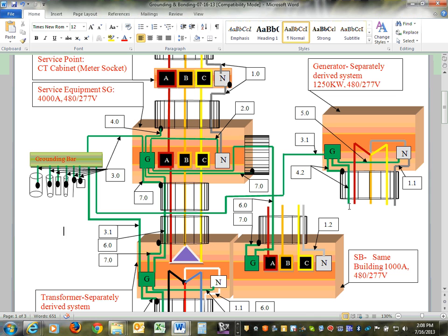So these are typically, guys, if you deal with parallel switchgear, you take your power out of these beasts, 1250 kW, in a conduit, and you land them into a parallel switchgear, and your first circuit breaker will be located inside the switchgear, right? Draw-out switchgear. If you have a smaller emergency generator sitting there, your circuit breaker disconnect will be located right at that generator. In a case like this, that 4.2 is going to be called the equipment grounding conductor. Any comments, guys, about 4.2?